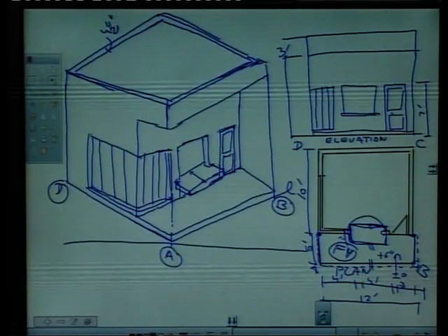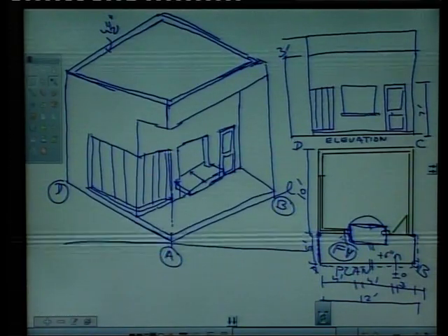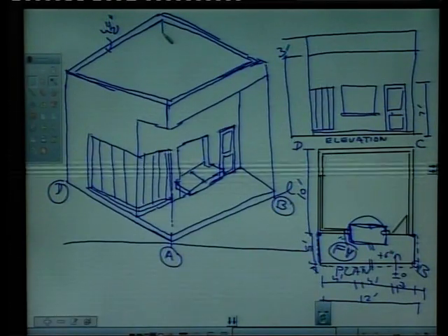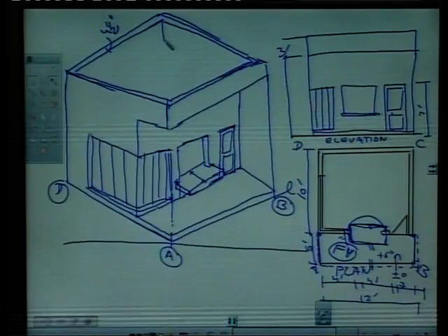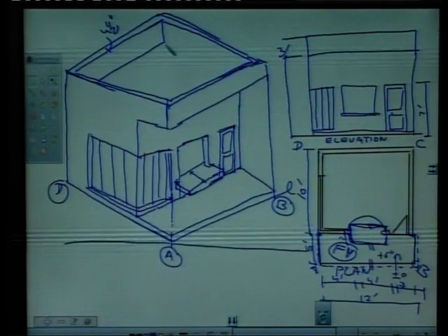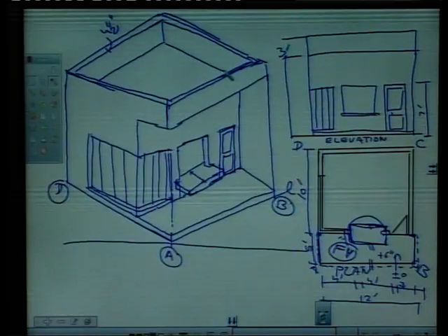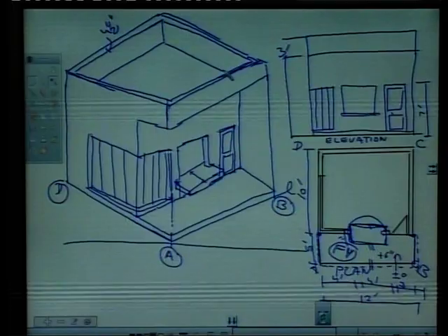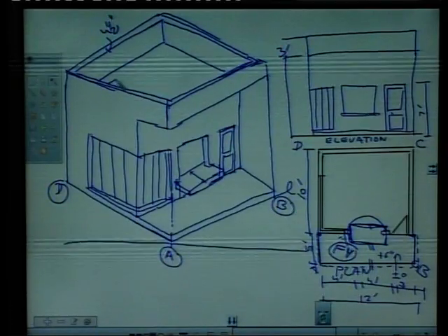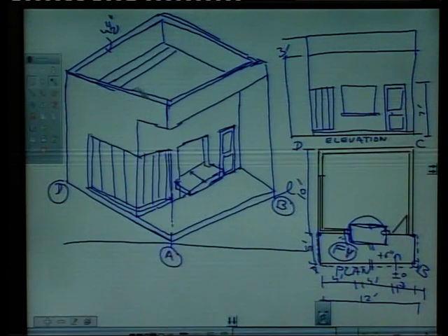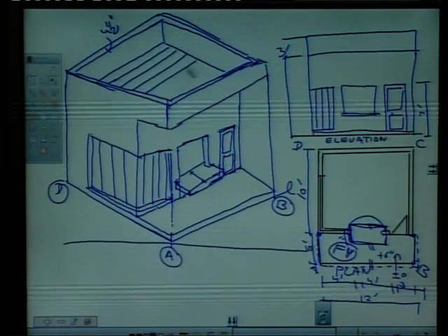Then as we know depth of the parapet is 3 feet, draw a vertical line from here, as vertical lines remain vertical, 3 feet, and draw a parallel line like this, and from here draw a parallel line like this, right. So, actually this will give us top of the security post or terrace of the security post.